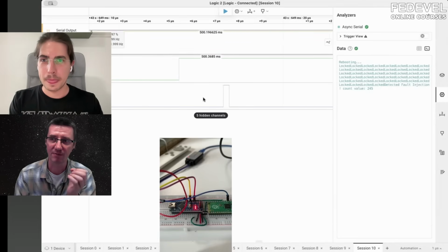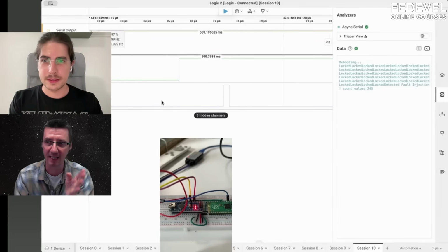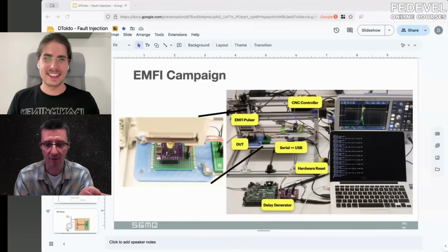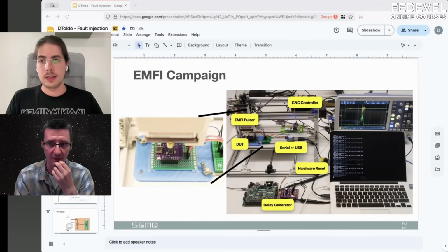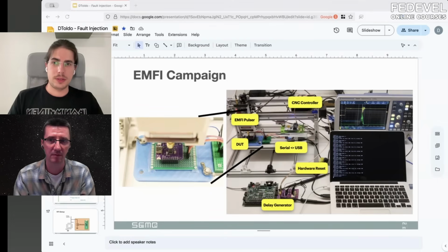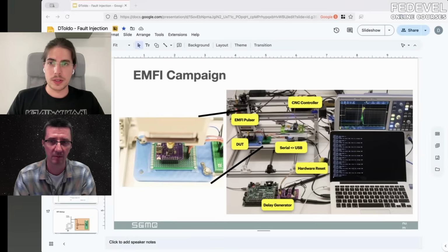What is very surprising for me is that the chip doesn't reset. That's super interesting, because it also means that if your power rail is poor quality, your board may look like it's working perfectly fine, but it may not be. There's actually a whole field of research that focuses on safety in this regard.